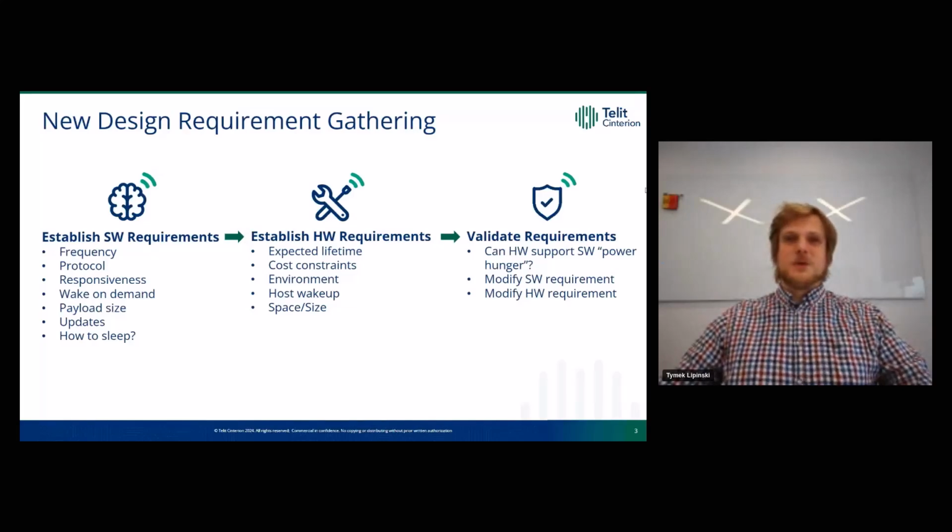We start off with requirement gathering. Firstly, we establish our software requirements. We have to define our frequency of communication, what kind of protocol we will be using, and the responsiveness of our device. Do we need to wake on demand from an external signal? How big will the payload be? How many updates do we need to provide and service? And most importantly, how to sleep and save energy.